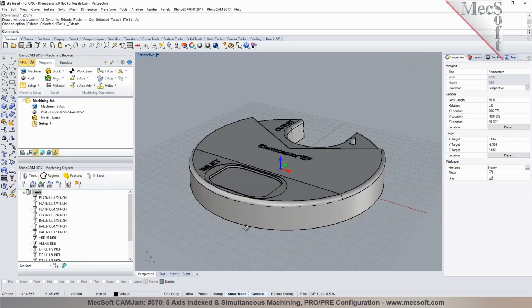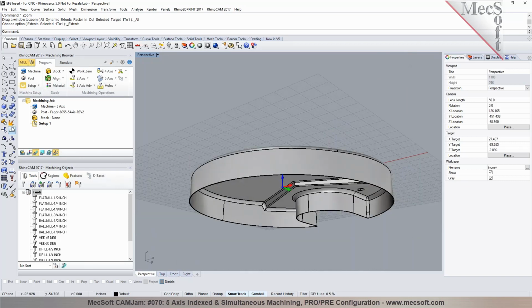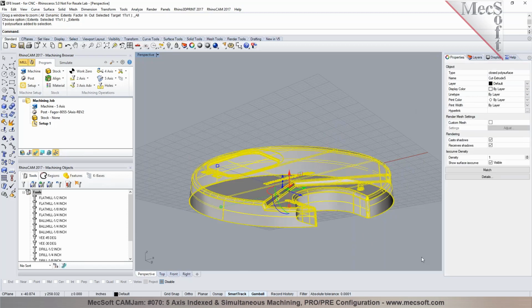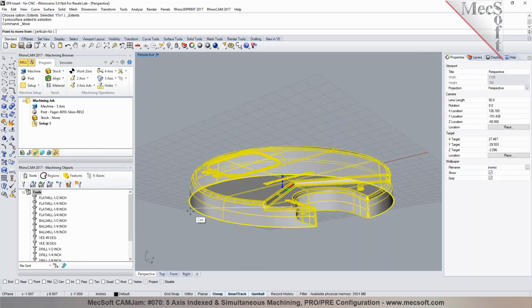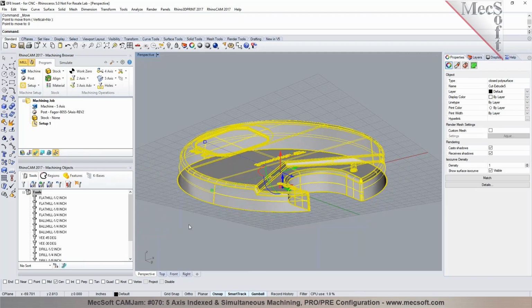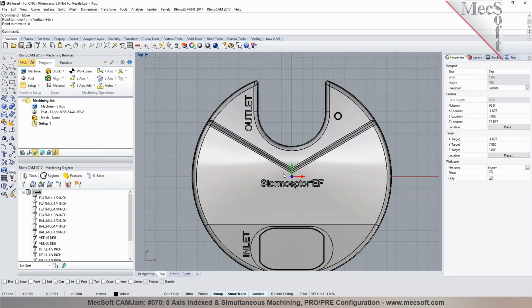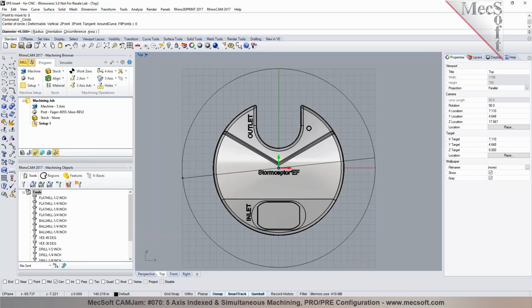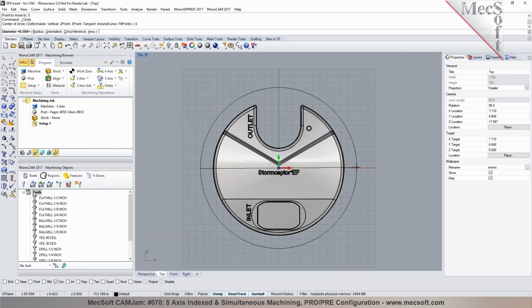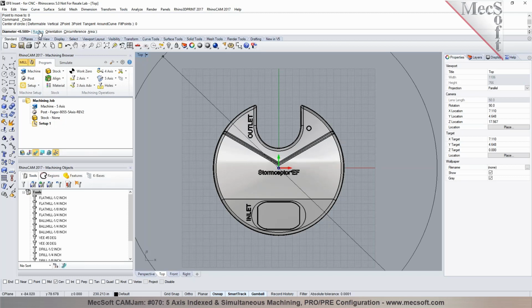So one of the ways I could do it, the easiest way for me, would be to select this part, and I can say I want to move the center point to the origin first. I'll do a transformation command in Rhino. I'll put the center at 0. Okay? So the center of that is at 0, and now I can define a circle and split it in 2 halves. I'm going to put a circle starting at 0 and then give it a radius. Would that be like a 48-inch radius or slightly 47.5 radius, right?